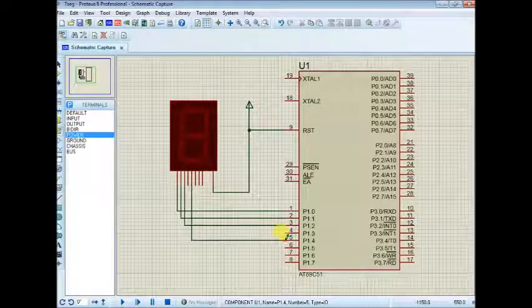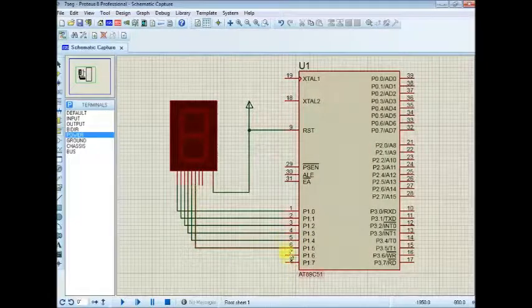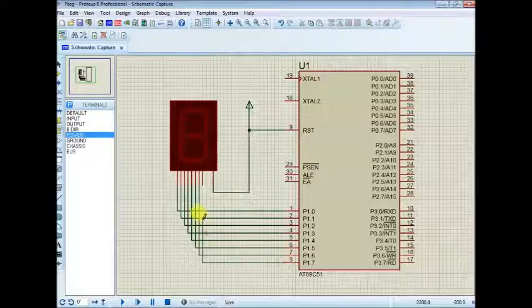various pins. Now one thing that we need to remember here is basically to display any particular data using the 7 segment display, we need only 7 pins, but here one extra pin is available, pin number 1. In case of common anode and common cathode, we need to put various values. Like in common anode connection, we are putting that pin as 1. In case of common cathode, we are putting that as 0. That we'll see later in the same tutorial.